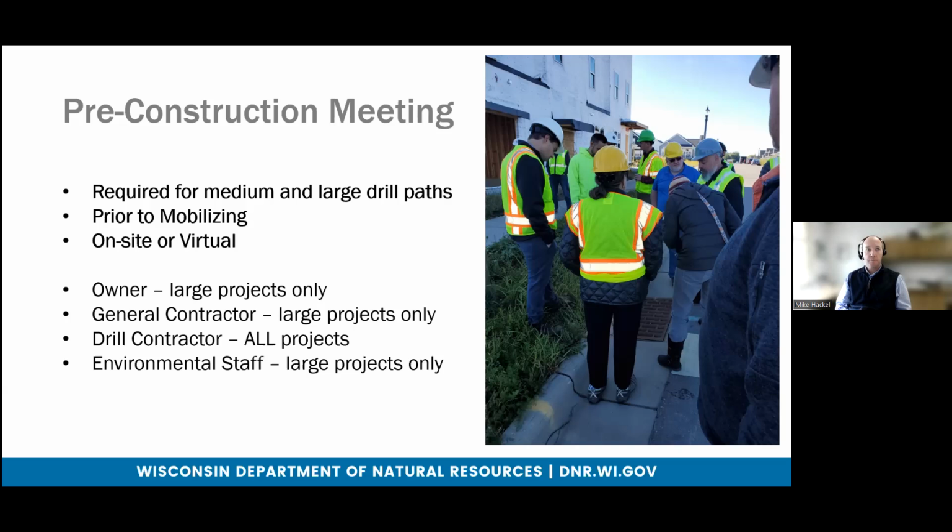and drill string areas. The spill plan and the IR plan need to be gone over at this meeting, depending on the boring size. You also want to talk about who's going to monitor for IR along the drill path, and also who is responsible for reporting throughout the course of construction. You also want to discuss the communication chain of command in terms of who's going to be notified should an IR happen. And the last topic would be discussing the restoration to complete the project, returning the site back to its original condition post-construction.